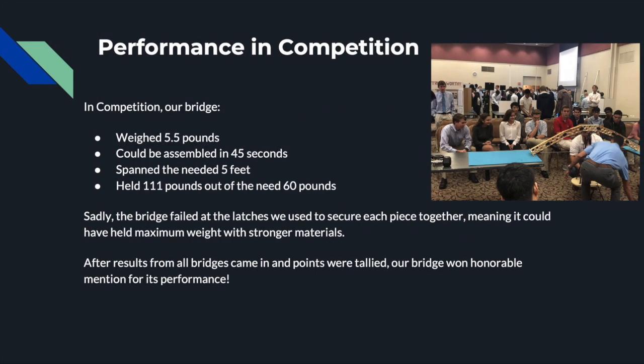At competition during FEDD, our bridge officially weighed in at 5.5 pounds. It could be assembled in around 45 seconds, spanned the required 5 feet, and held 111 pounds out of the required 60. Sadly, our bridge failed at the latches we used to secure each piece of wood together, meaning it could have held the maximum weight with stronger materials. After the results from all the bridges came in and points were tallied, our bridge won honorable mention for its performance. Following is a video of our bridge during competition.